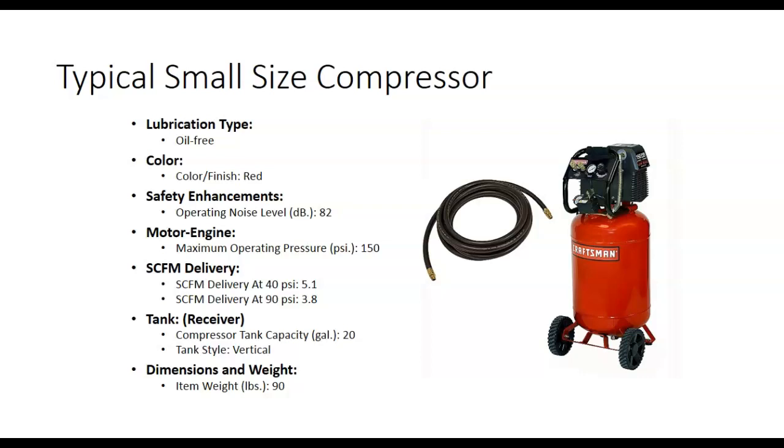And what they found out a long time ago on compressors is that the further you go up in altitude, the compressor can't put out the flow, because the molecules are not, it can't compress them as much, right? Understand? So that standard cubic feet per minute is at sea level.